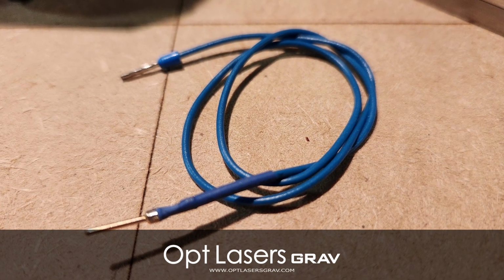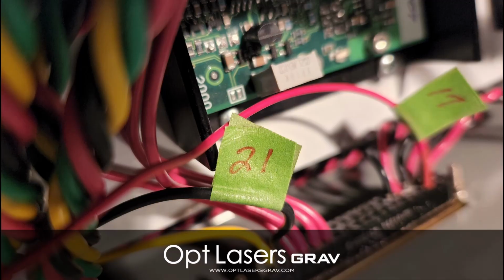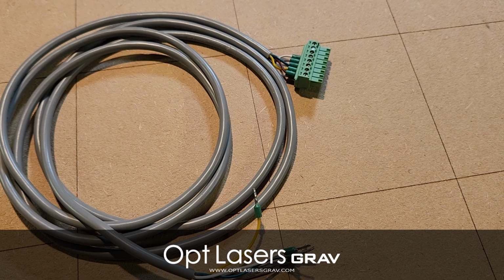The pre-wired pins that we're going to install will look something like this. From inside the box, locate the connector. Each pin location on the connector is marked and identified. Locate pin position 17 or 21. If they are empty, install this pin. From the outside, pull the pin snugly into place. A better option is to use a correct pin setting tool.